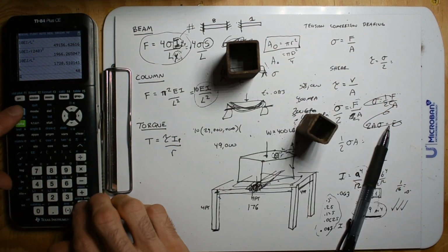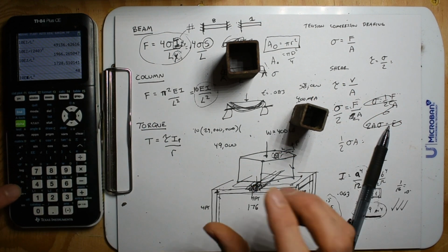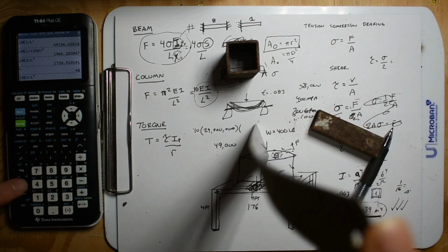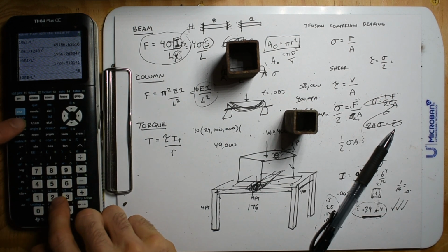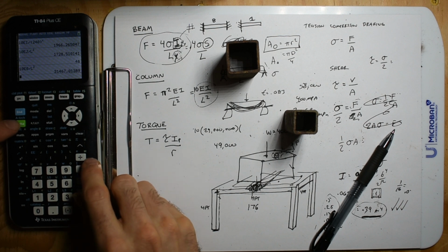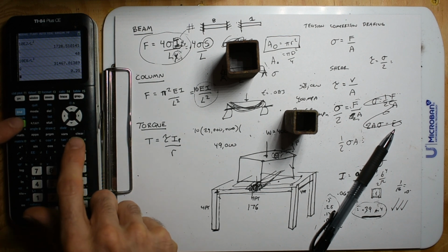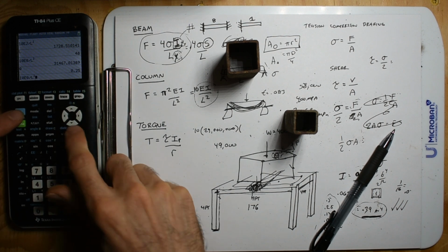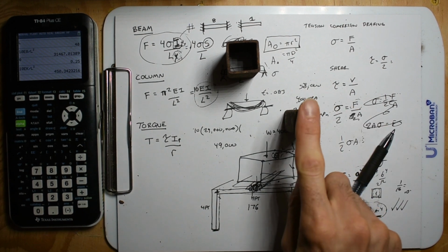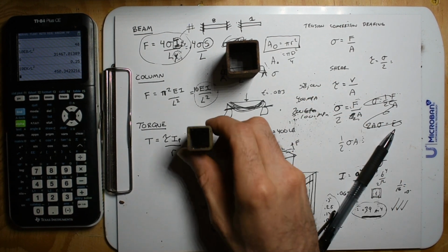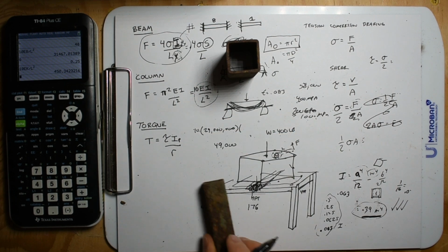But now let's go to this one and see if we could even make it out of that, and 4 feet's not gonna do this. Not gonna make it turn into an archer's bow. That was a different value. So we did I, J, and now we're at K. Okay, so we could do 450 pounds on each of these. And heck yeah, our thing only weighs 400 pounds. So even if our table was made out of that, that's pretty sweet.